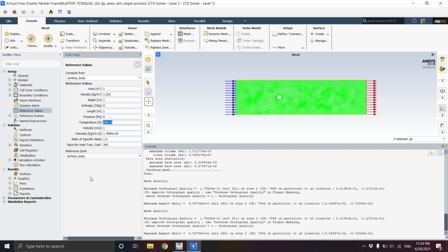Right now it's set up as an atmospheric temperature. So you're not gonna change it right now. You have your viscosity again right here if you want to take the value in order for you to make calculations and everything. So that's most of the setup for your ANSYS problem, for any problem on Fluent. So we'll continue on the next tutorials.